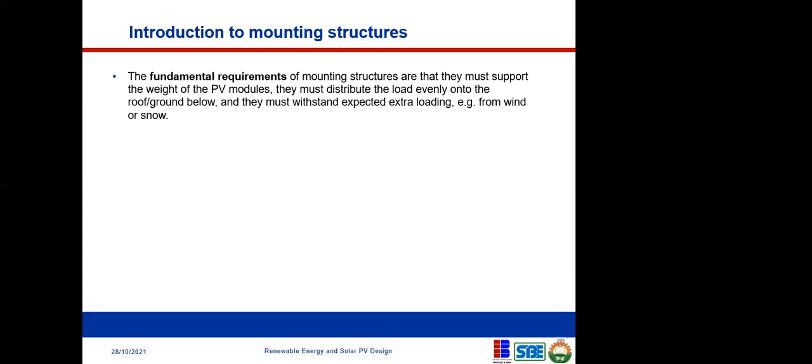Mind you that these PV panels have weight, okay? And you're putting them on top of a roof. Now, it may not have been envisaged in the design of that structure that this roof was going to have such weight on it. So as an engineer, you need to be sure that whatever structure you're putting the panel on has the capability to withstand that weight, okay? So it's very important. Otherwise, you add extra load to a structure whose structural integrity you don't know, which can lead to engineering failure. So it's important we look into all of that.